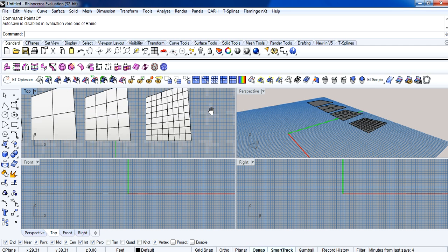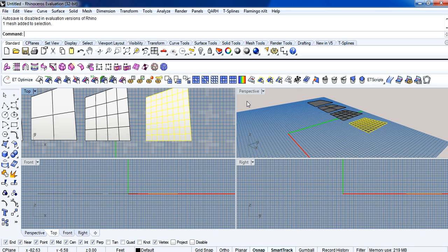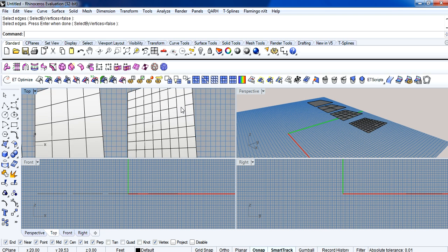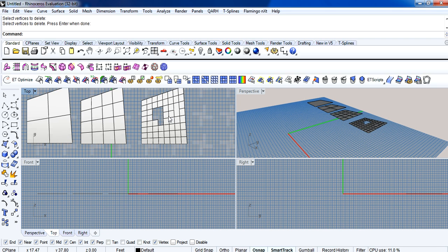And let me show you some other little basic tools. So here we take this mesh, some other tools over here. It's the deleting tools, so we can maybe delete a mesh edge line, push Enter. You can delete each one of these faces, so I'll do that again to show you here. Delete that one if you want. And these ones, you can delete a point with all lines around it. So this one will just take a hole out of it actually, or you can delete a whole polyline. So it deletes the whole line there.